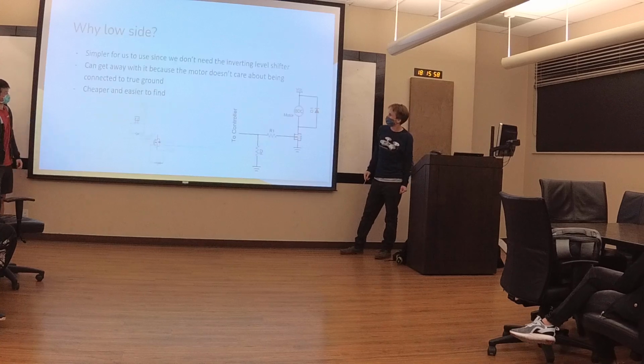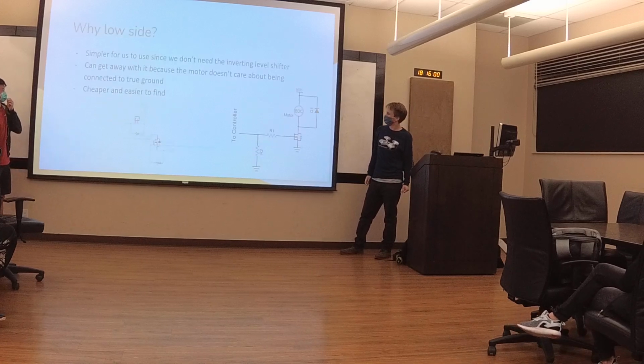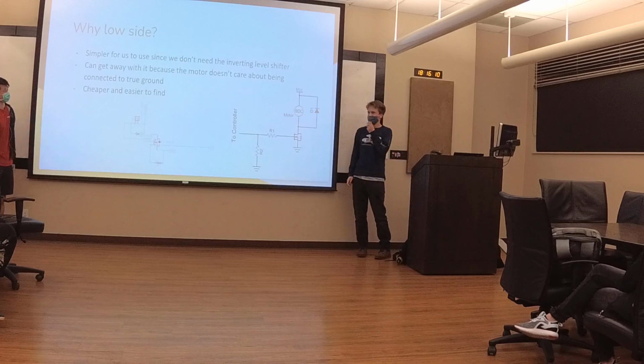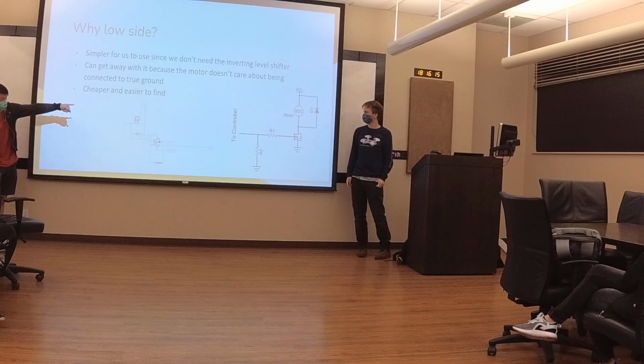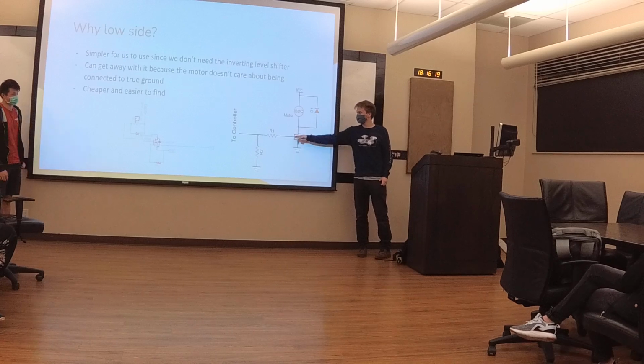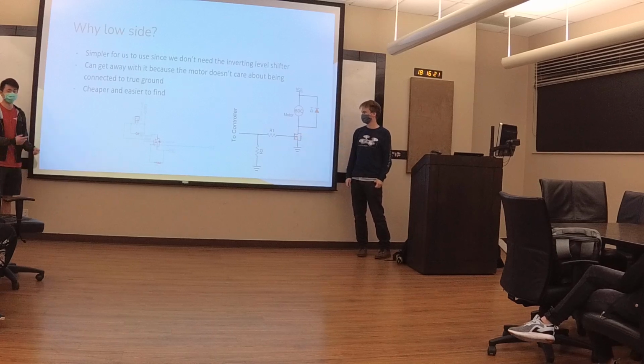Okay, yeah, we do talk a little bit more about having a true ground here. So these are, as Alexa was saying, the reasons why we want to use a low side driver. First off, you don't need the inverting level shifter, which means cheaper and less complicated. And second, about the true ground idea, our motor's negative terminal is connected to the NMOS drain rather than the actual ground, which, as he said, doesn't matter in our case.